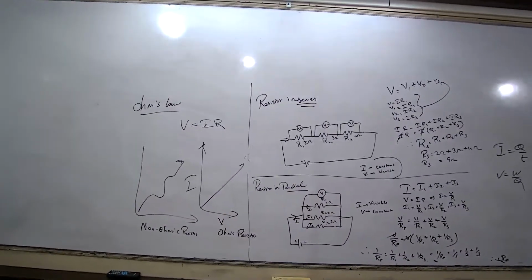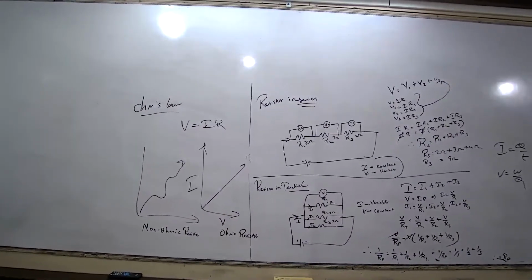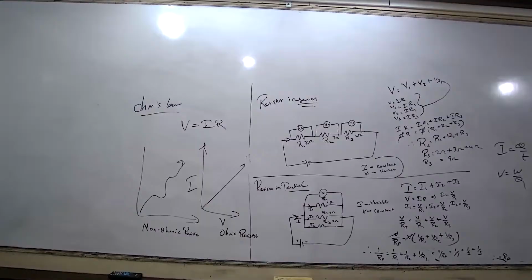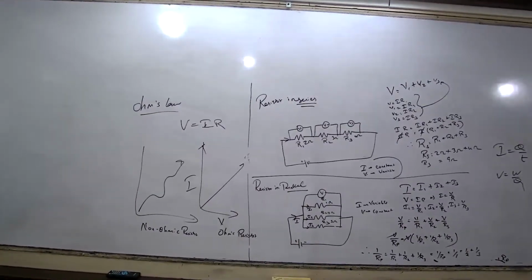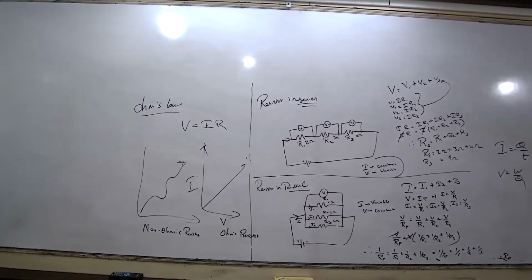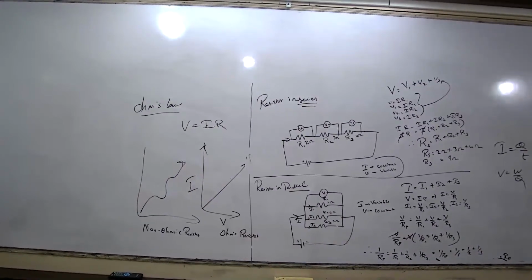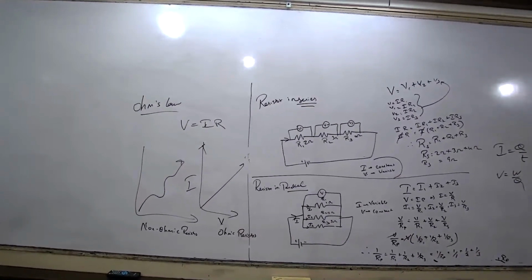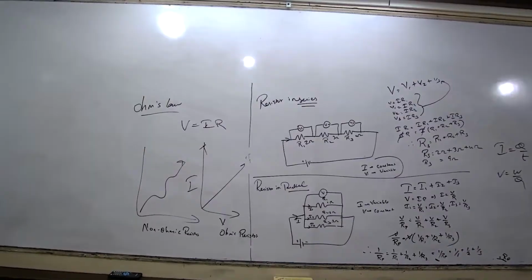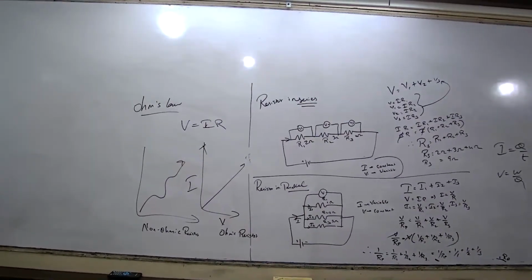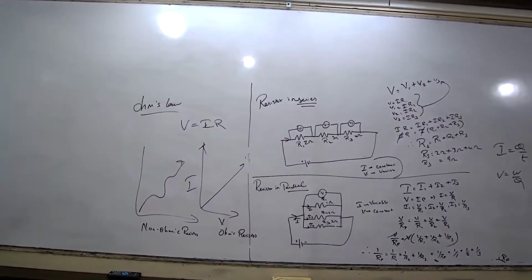Then capacitor and resistor, you will get confused. Capacitor and resistor is vice versa. Think of it in your mind. If it is plus for 1 by R1, then for capacitor it is 1 by C1. So when it is parallel, that will be the series manner. Plus 1 by C1 plus 1 by C2 plus 1 by C3, like that. So in engineering, a combination of capacitors and resistors will also be there.